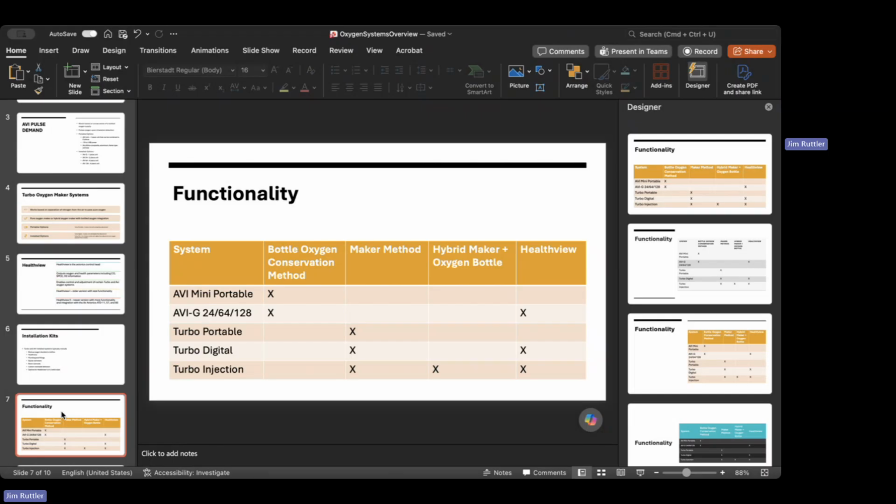Part 23 limits for all systems. For the portable, there's no limit. It's the same technology as all the other systems, but because it's portable and not attached directly to ship power, but rather indirectly using a USB port on the aircraft, there's no limit for Part 23. But if you hook the power up directly to the aircraft power bus, bypassing a USB power source or power receptacle on the aircraft, then you are bound by the Part 23 limitations.